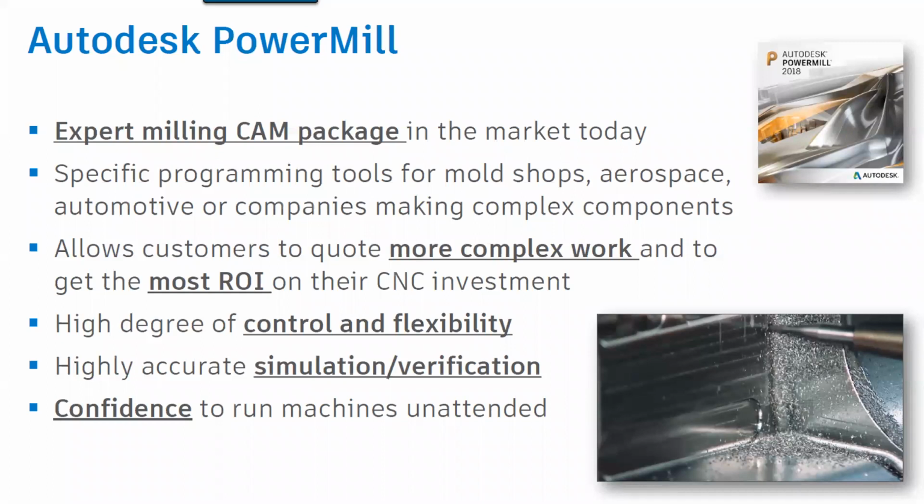Another added benefit to PowerMill is that it actually does machine simulation as well, right? So especially running some of these more complicated 5-axis parts, one of the biggest worries when you're programming is, is my tool going to collide with the part or with the machine itself? Right. So again, with PowerMill, it does have machine simulation, and that's just another safety net, if you will, for your programmers that are going to be out on the shop floor.